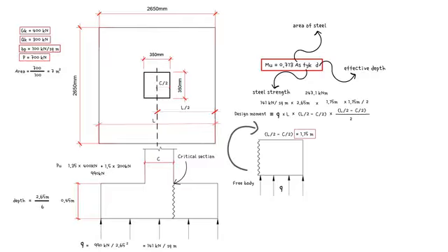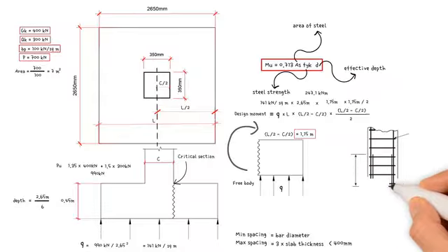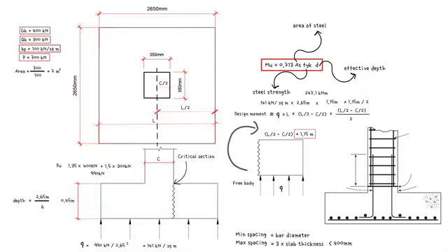There are a few simple rules to follow when it comes to reinforcement spacing. If the bars are too close, they impede the placing and compacting of the concrete, causing voids to form. Minimum spacing of bars equals bar diameter, or maximum size of aggregate plus 5 mm. Maximum spacing of flexural reinforcement in slabs equals 3 times slab thickness, less than 400 mm. Maximum spacing of shear links equals 0.75 times beam effective depth. The reinforcement is, of course, placed in the tensile face of the foundation, which is the bottom. The foundation will also contain the starter bars for the column reinforcement.